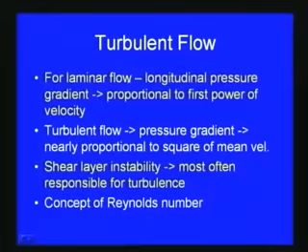As we can see in this slide, for laminar flow the longitudinal pressure gradient is proportional to the first power of velocity, as we have already seen. But in turbulent flow, due to the intermixing and various variations of parameters, the pressure gradient is nearly proportional to the square of the mean velocity.